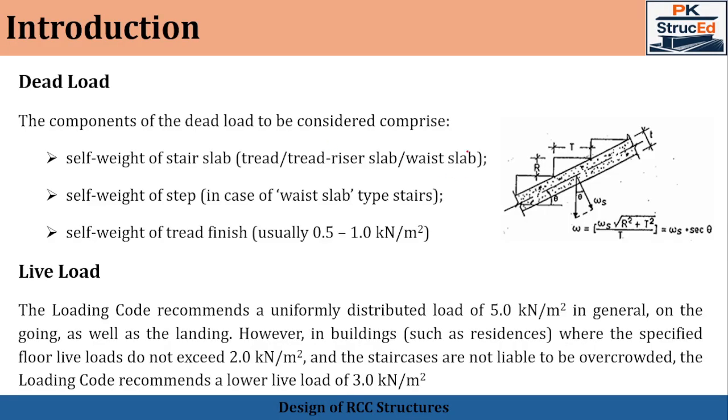Why it has to be carefully evaluated is that here the slab orientation is inclined, not horizontal like conventional slabs. So if I want to find the self weight of the slab, we use the relation: thickness of the slab into unit weight of the concrete.